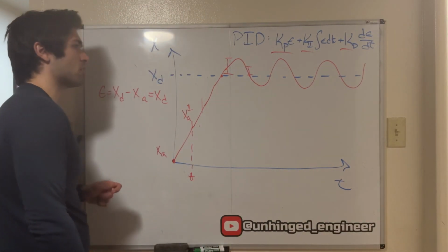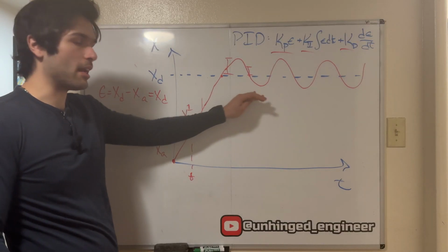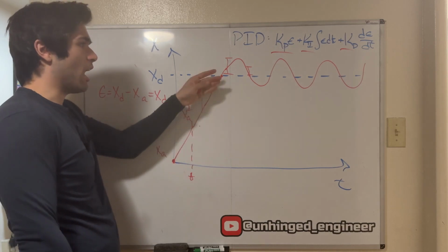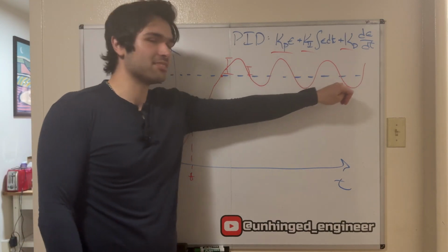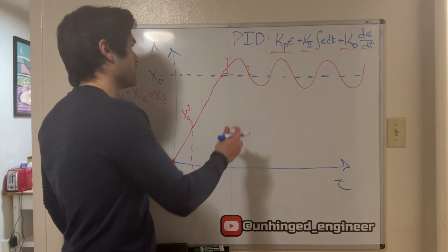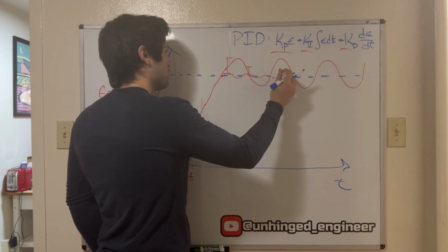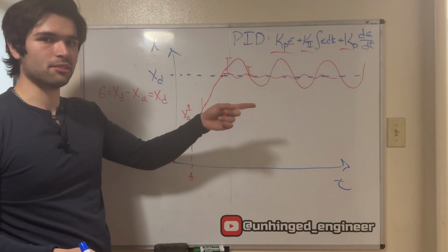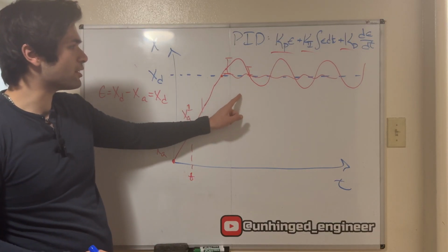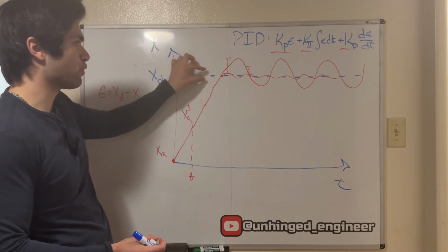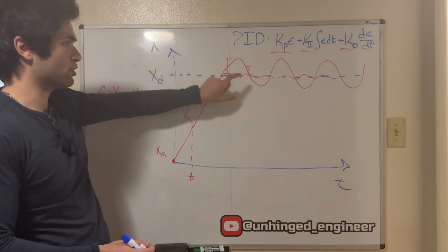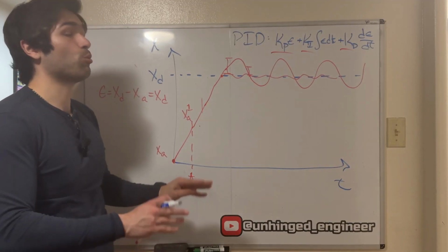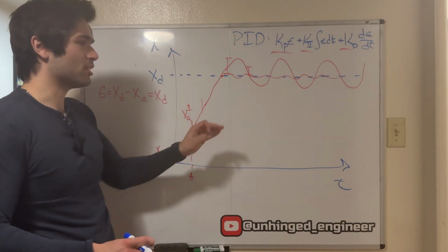Based on the frequency of your system and how strong this gain is, excuse me, K sub P, we're just going to oscillate about that set point. Now, if this is really tight, that might be okay, but we can do better than this, right? We can have a system that actually converges. So this isn't going to converge, it's just going to oscillate around the set point, if we're lucky, for reasons we'll get to shortly. So this is not ideal.